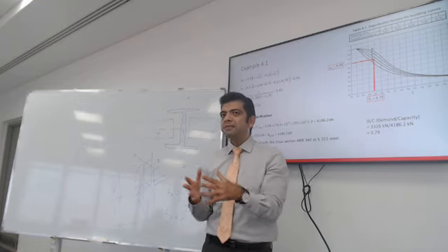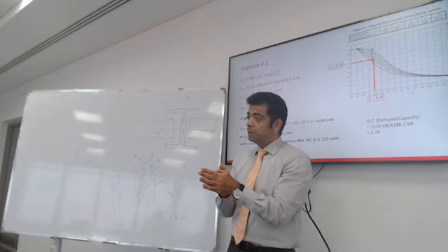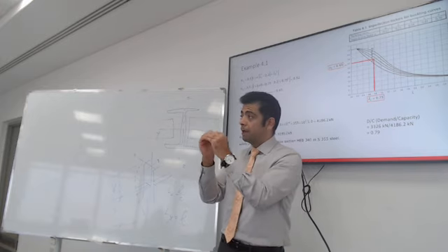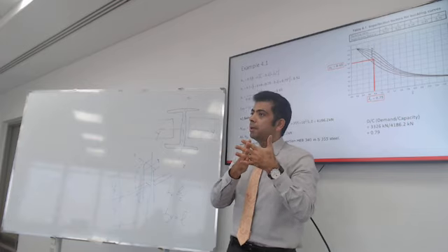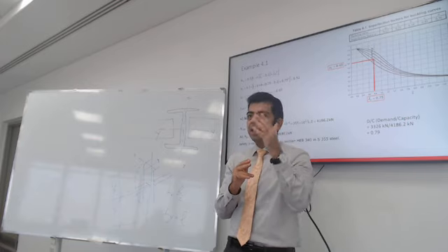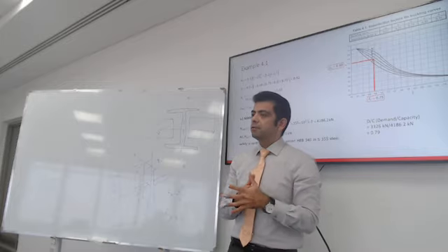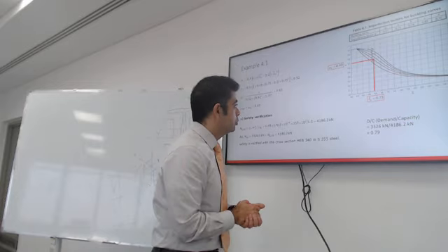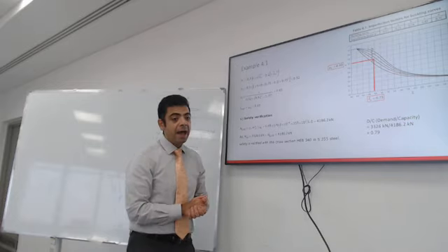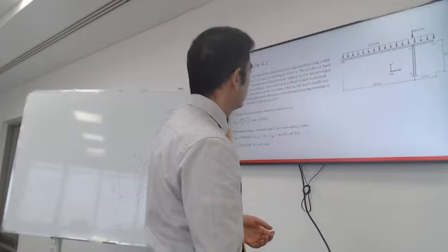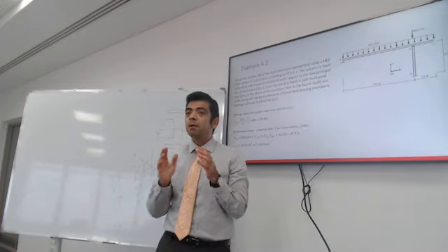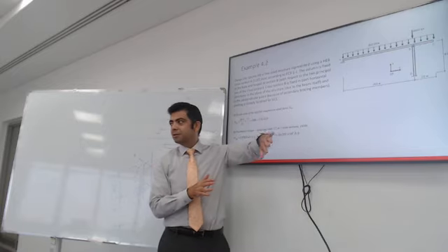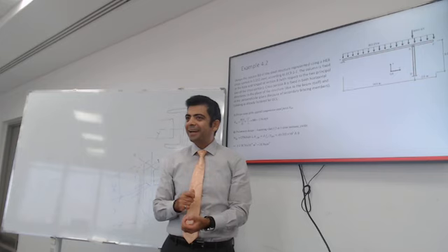So what I want to say is 0.9 is reasonable, and you can argue with your clients that if you push it north of 0.9, the connections are going to become challenging. So you're going to think ahead and leave some room for the design of the connections. All right, so that's pretty much what I wanted to talk about. I have one more example for you. You can go through it. It's pretty much the same process. In order for this to make sense to you, just make sure that you cover the answers and see if you can get the actual values.